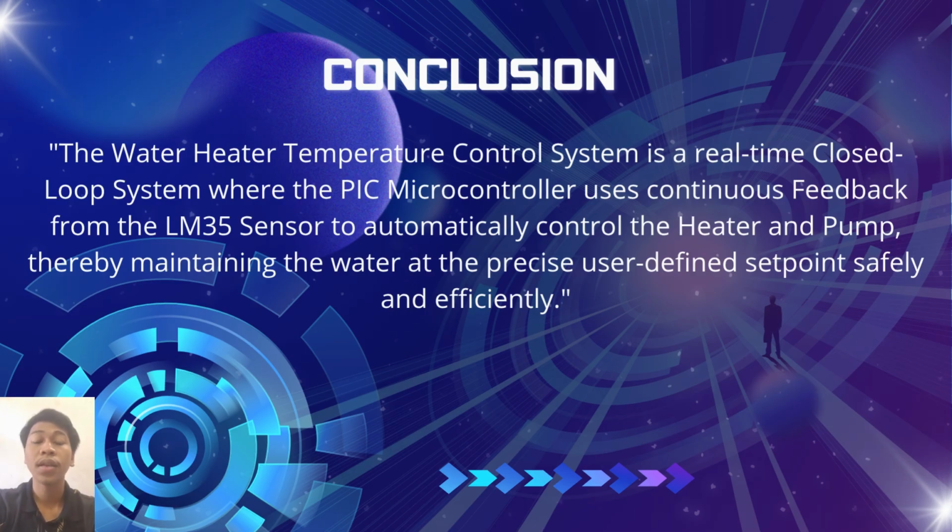For the conclusion, the water heater temperature control system is a real-time closed-loop system where the PIC uses feedback from the LM35 sensor to automatically control the heater and pump, maintaining the water at the precise user-defined set point safely and efficiently. That's all for me.